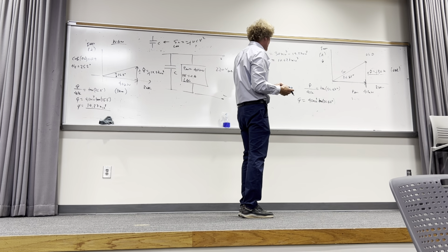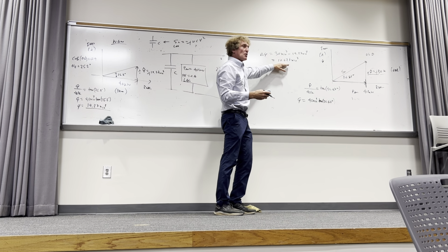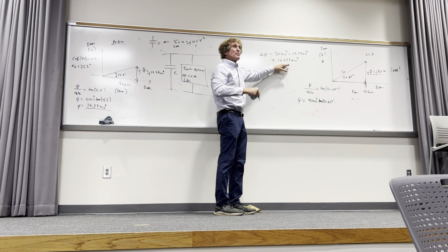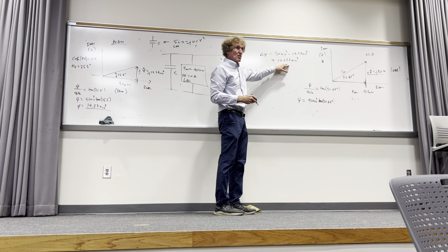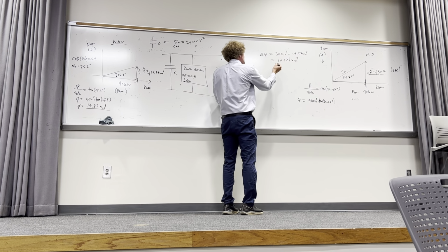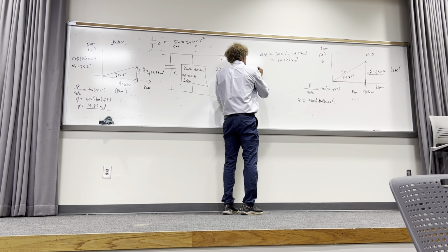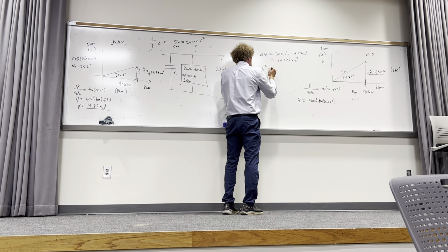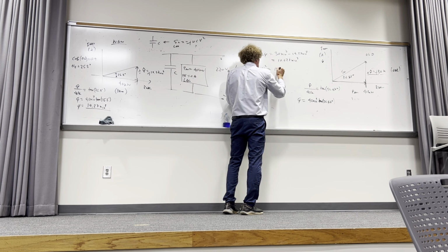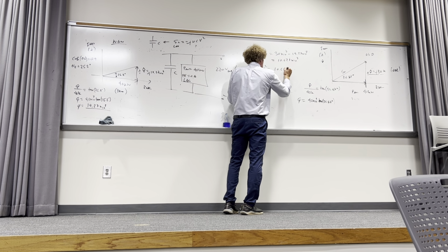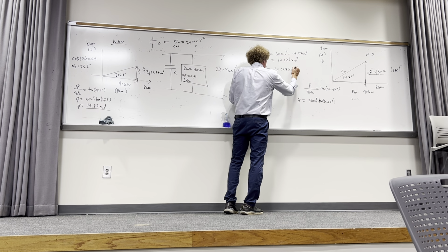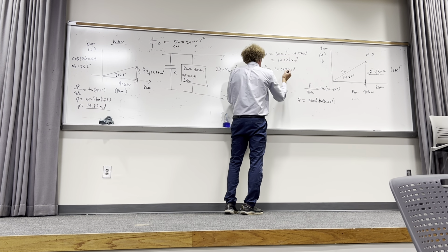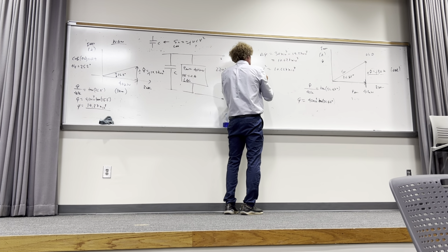So what I can do here is this. I know that's the total change, and I know the capacitor is going to cause it. Do y'all follow me, class? So what I'm going to do is just set omega C times the voltage squared equal to 10.627 times 10 to the third, and then I'll solve for C.